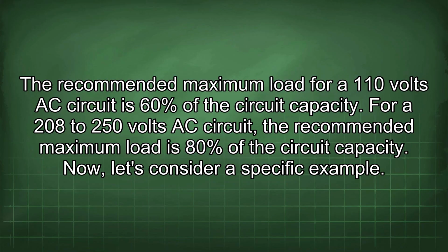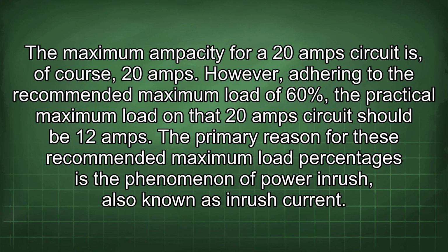The recommended maximum load for a 110 volts AC circuit is 60% of the circuit capacity. For a 208 to 250 volts AC circuit, the recommended maximum load is 80% of the circuit capacity. Now let's consider a specific example. The maximum ampacity for a 20 amp circuit is, of course, 20 amps.